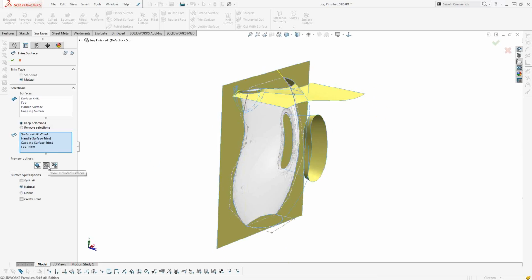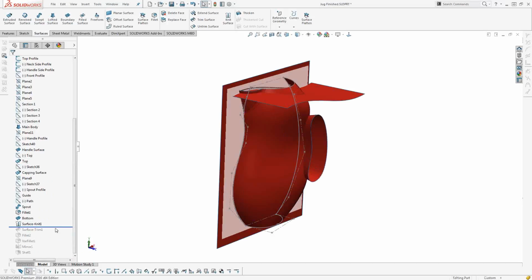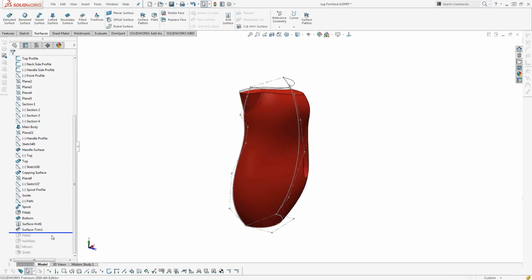These trimming options are also available within the body trim tool as well. Let me go ahead and hit my green checkbox. I've got my nice resulting trim surface here. Okay. Along with that, after we create the trim surface, we may want to come in, knit them all together, and apply some different fillets along the part.